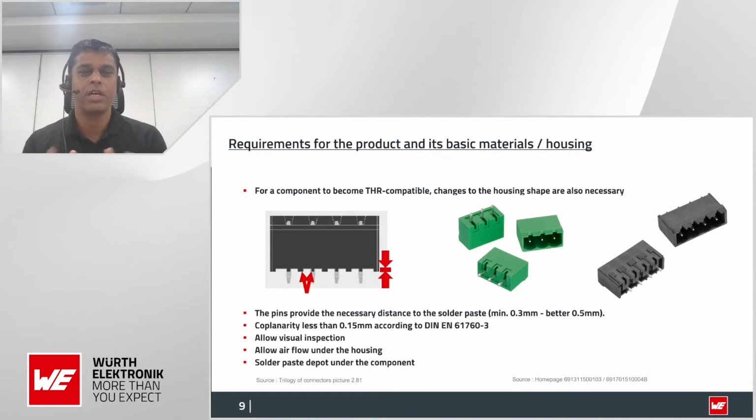So if you have a close look, you can see the first thing, when you talk about the housings on the right hand side, the enclosure size, you can see exactly where some plastic standoffs have been designed. Why they have been designed is that when you place a THR component on the surface of the PCB, it allows the solder paste process, I mean the reflow soldering process, you can say the through hole reflow process, to go very smoothly, and air can also pass easily without creating any bubbles.